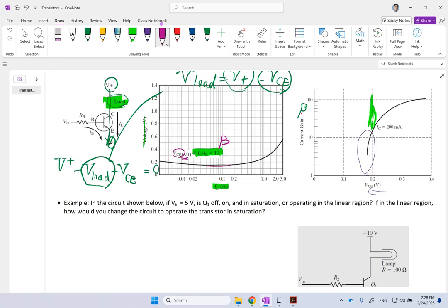Okay, it's very minimum. If you plot this for other ranges of IC, clearly in the saturation range it's minimum, and it depends on the IC itself. But you see, if you look at this range, it's mostly somewhere around 0.2. So if you work with the gain of 10 or something, the voltage CE is also very minimal, about 0.2.